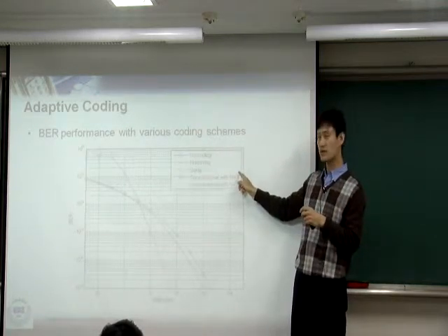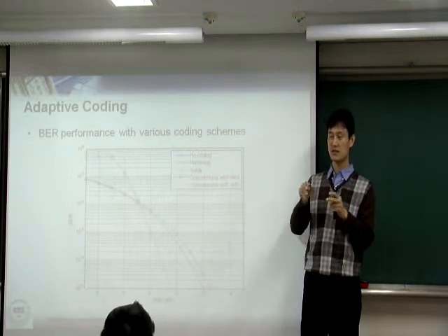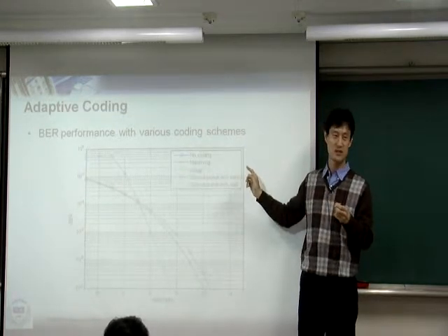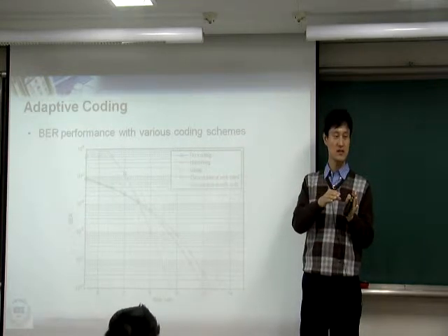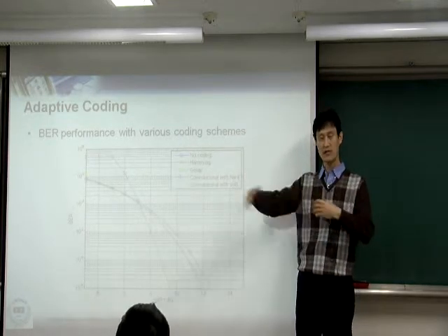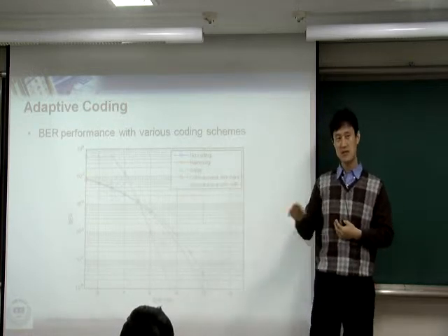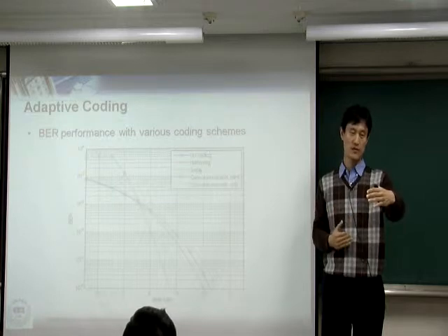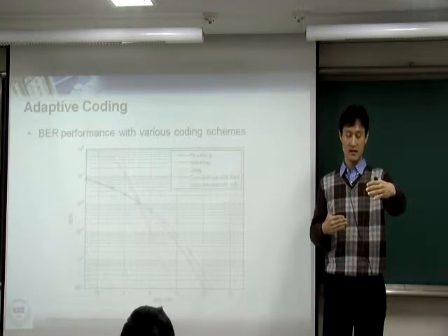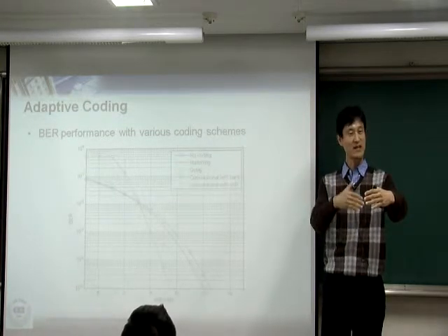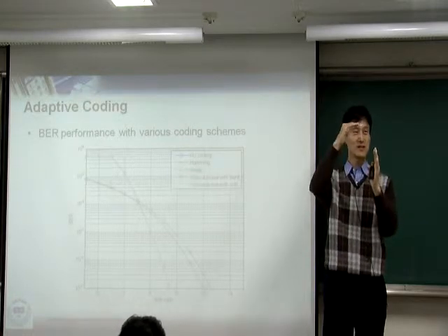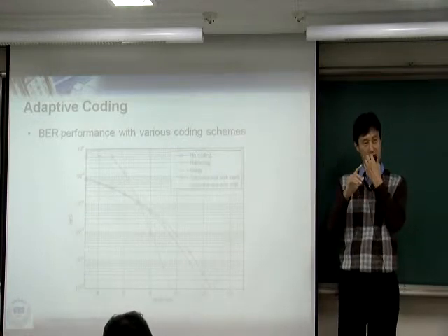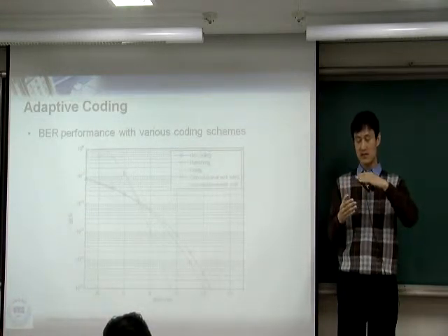You can use a hard decision or a soft decision. A hard decision is a 0 or 1. Even when it is a temporary decision, you make a 0 or 1 decision, and that decision now influences the rest of the bits. A soft decision basically says that you are not going to make a temporary decision like 0 or 1. You make a decision like it's likely 0 or likely 1. There are several steps; typically we use 8 different levels, 0 to 7.